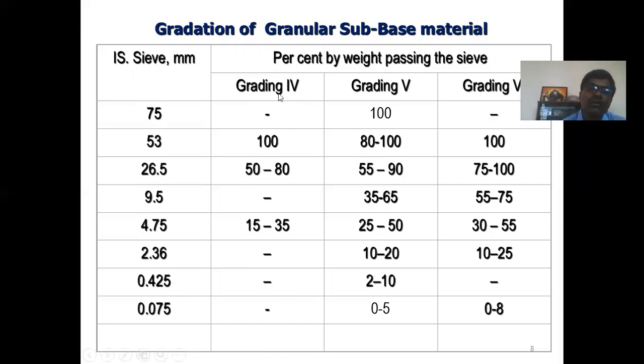So we have open graded, coarse graded GSB and close graded GSB, dense graded GSB. So here you can see it is close graded. But irrespective of the coarse grade or the close grade, GSB layer serves the purpose of the drainage, the permeability of the infiltrated water.